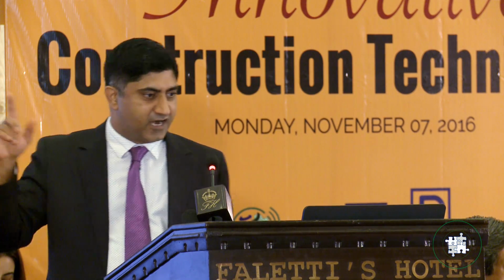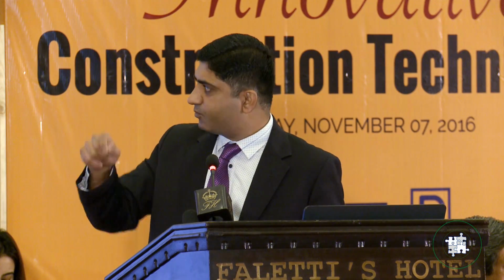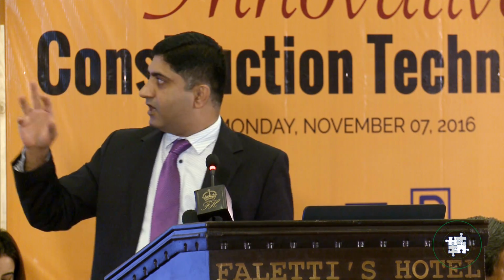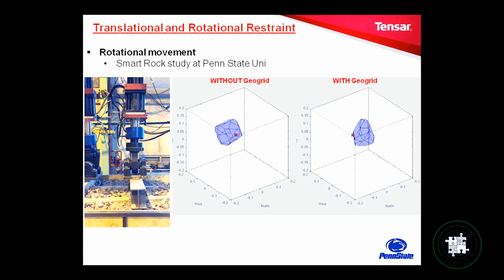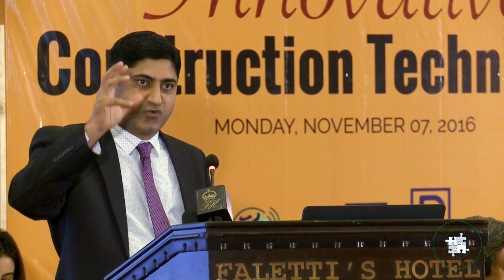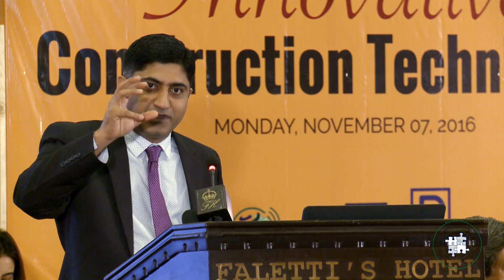On the left-hand side is the real rig. The rig operates, and as a result of the cyclic loading, without grid and with grid section, you can clearly see the movement of particle. After a certain time, this movement will increase in the unstabilized section, while in the section stabilized with the geo-grid, the particles still start rotation at their own place. They don't leave their place.